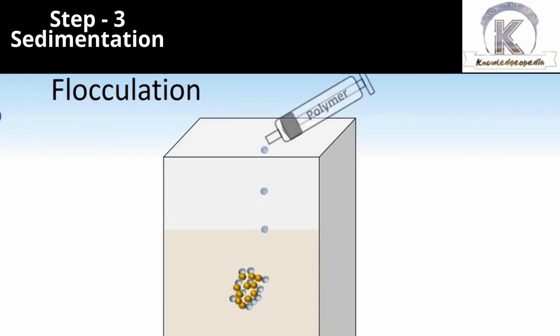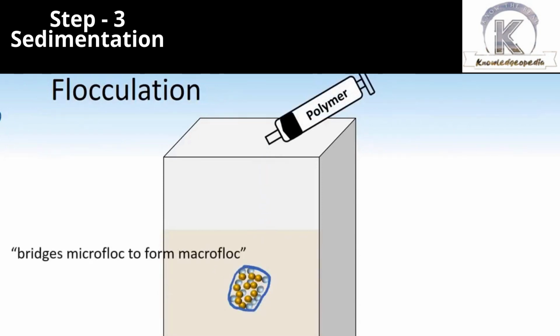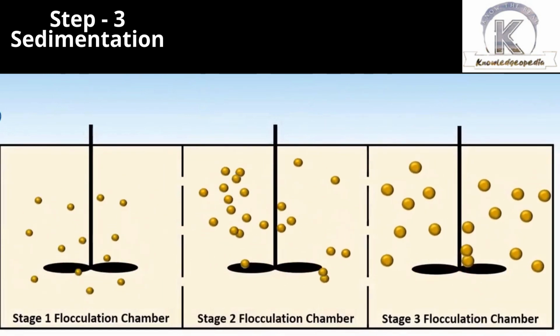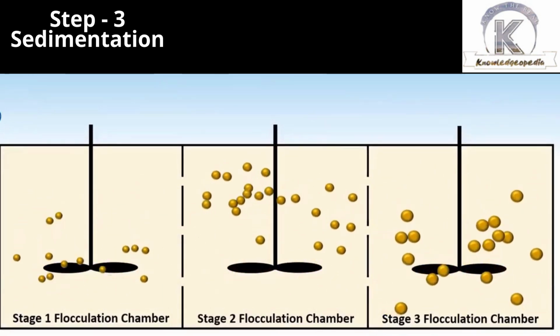The tank that creates this phenomenon of creating flocks is called a flocculator, and the process of mixing coagulants like alum and polymer is called coagulation. The comparatively clean water is then collected by overflowing from the flocculation tank and flowing through a channel, the same as in the primary sedimentation tank, and goes for the next level of purification.